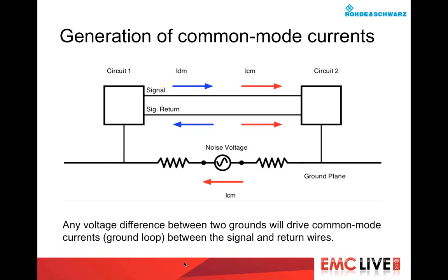If you take a look at any ground return structure or ground plane, you'll realize that there is going to be a certain impedance across any two points, and anytime you have an impedance, it will create small voltage sources, and these voltage sources are what push the common mode currents. There are several ways of creating common mode currents. This is one of them. But anytime you have unbalanced geometries, that can cause common mode currents in your transmission lines, for example.